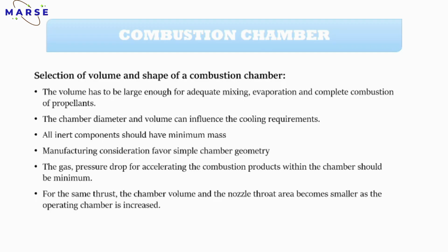The next one is that manufacturing considerations favor a simple chamber geometry. It should be a simple geometry. If the geometry is simple, then obviously the combustion process tends to be simple. The gas pressure drop for accelerating the combustion products within the chamber should be minimized.